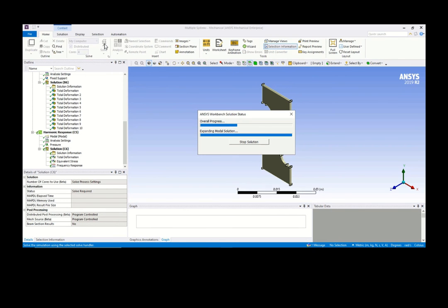If you run this specimen at 356 hertz, the stress induced is 570 times larger than if you consider it as statics. So the fatigue will happen far earlier, only 22 cycles. But if I'm running at 10 hertz, you have to rerun and see the deformation and the stress induced at 10 hertz.